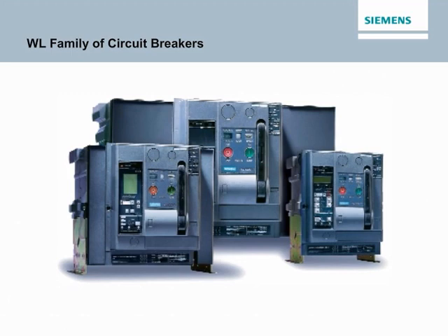Another category of low voltage circuit breakers is the LV power circuit breaker. LV power circuit breakers are generally drawer-out mounted and may be used in switchboards or switchgear. LV power circuit breakers intended for the U.S. market conform to American National Standards Institute, ANSI, standards C37.13, C37.16, C37.17, and C37.50, and National Electrical Manufacturers Association NEMA standard SG3. The corresponding UL specification for LV power circuit breakers is UL 1066.